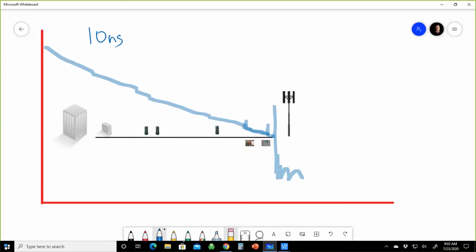So what does pulse width mean? An OTDR, as I mentioned before, sends out a pulse of light, and it sends it out measured in time. So a 5 nanosecond pulse width means the laser turns on and bursts for 5 seconds and turns off. 5 nanoseconds rather. So it's very, very fast. So we're talking about a very, very fast signal. So you're bursting really, really fast, which is a lot of sampling because each pulse is sampling the fiber, right? That's 10 nanoseconds. It's 5 nanoseconds.